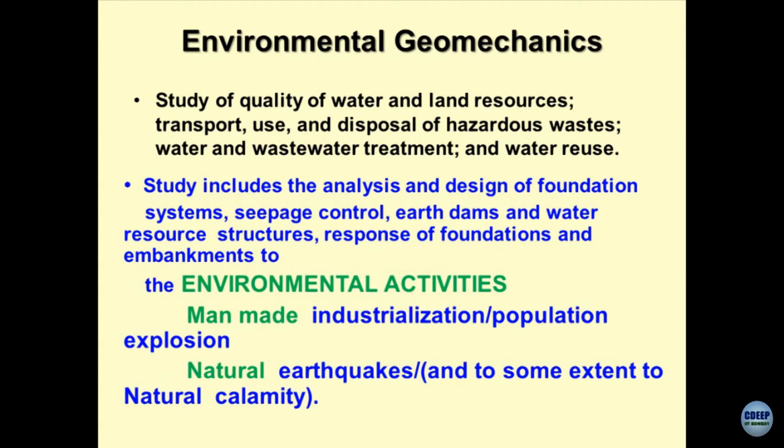Anything which comes to your mind apart from earthquakes? Hurricanes and tsunamis are playing a very important role. I have been dealing with several examples in our own country where post-tsunami rehabilitation, particularly in the Andaman and Nicobar area, became a very big challenge. Just to give you a quick example, a tsunami brings a lot of sediments along with it, and these sediments get deposited on the coastline, and now the infrastructure on these loose unconsolidated sediments is going to be a very big question mark.